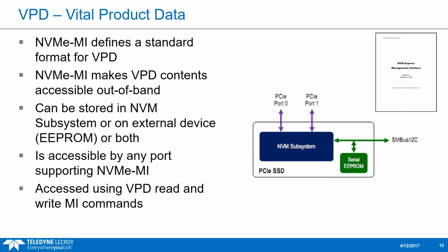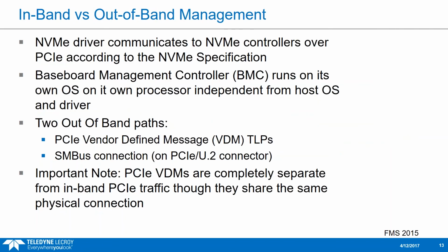So the vital product data should be accessible by any port that supports NVMe Management Interface, and it uses special VPD read and write management interface commands. As we'll see later, those commands will be transported over MCTP. We'll see that in a moment.